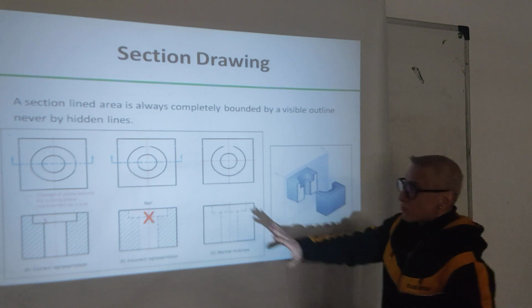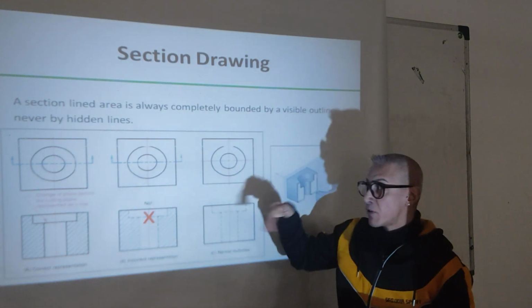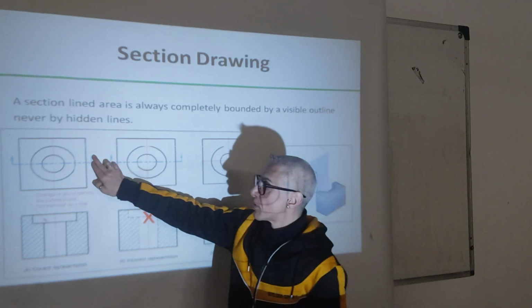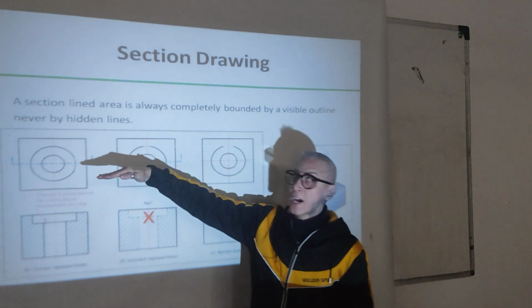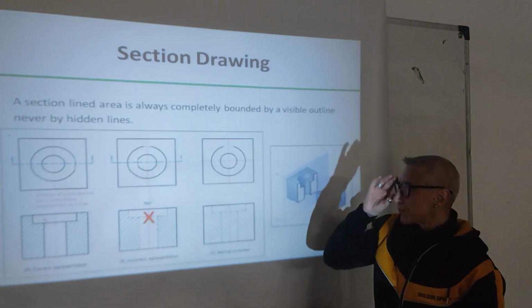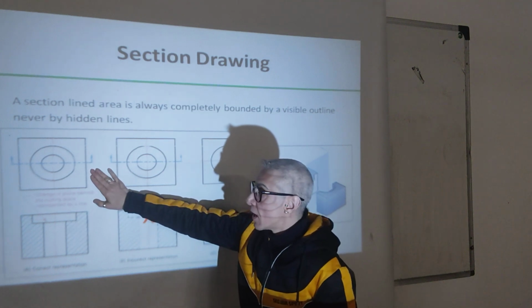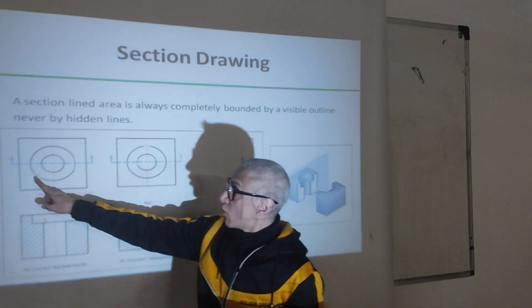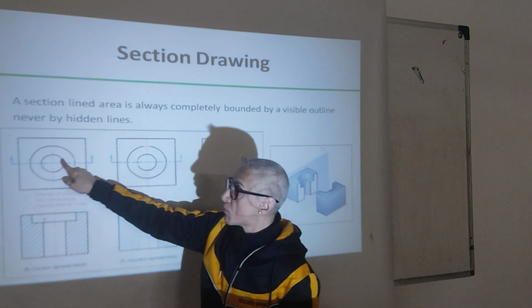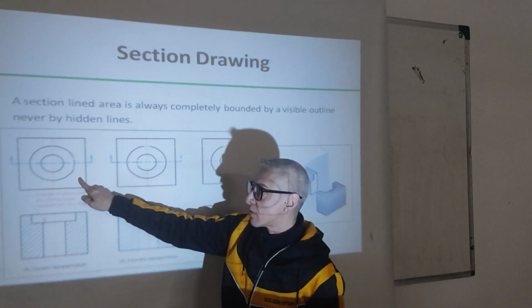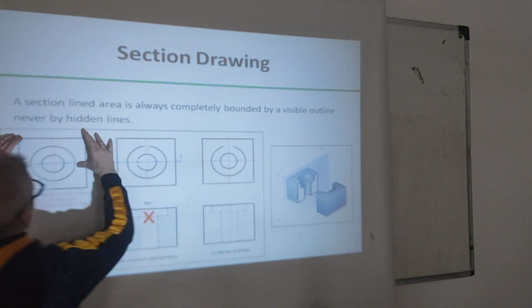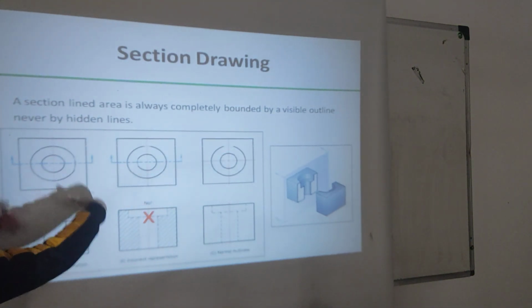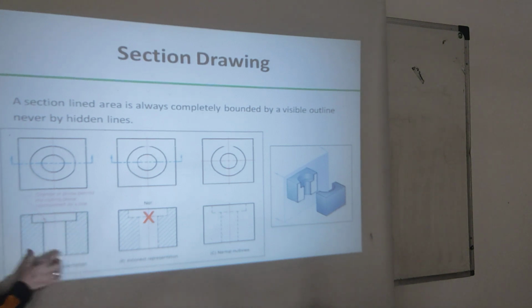Now, we already mentioned part of this, but I will repeat it. So we have a line that shows where we are cutting the object. Here, the arrows show up. That means we are keeping this part and we are deleting this part. So this part we are drawing here will be taken, rotated and placed here as opened. And this is here the solid material.